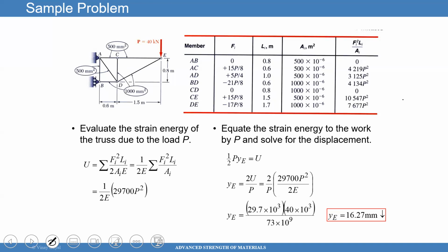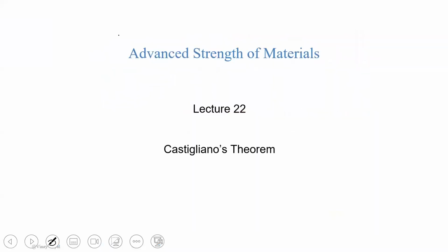That's an excellent question. Can I find the deflection anywhere else? I'll cover that. And I'll show you the method. It's called the method of Castigliano. What we're going to do, we're going to put a fake load that equals 0. It's weird, but you apply, say I want to know the deflection in point C here, where I circled it. And I'm going to apply a fake load here, Q. We call that a dummy load because it's fake. And then you do all your calculations, assuming that load Q is there. I won't show it here, but you'll see how we're going to do it. It's kind of cool, actually. Okay, great. All right, that takes me to Castigliano's theorem.